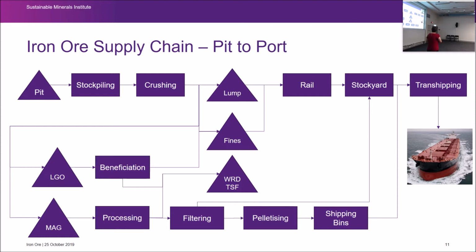Low grade iron ore, which is usually anything less than about 56% Fe, down to about 40 to 42%, gets stockpiled separately in the process. Again, in this beneficiation process, the aim is to produce your lump and fines products greater than 60% Fe, while maximizing your lump portion of it.